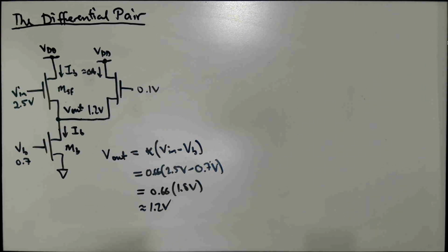Well, not really. We still have minus 1.1 volts of gate to source voltage, and that's not going to give us any channel current. In fact, we can bring this up considerably. We can say, well, what about 1.2 volts on the gate?